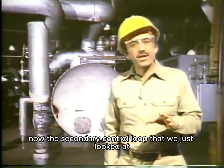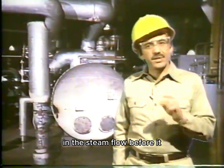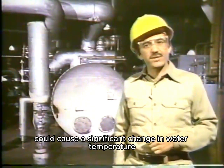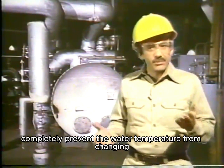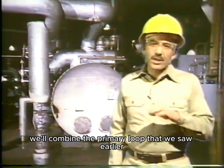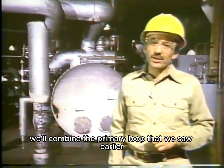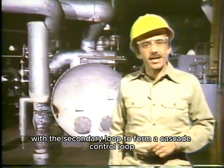Now, the secondary control loop that we just looked at was able to correct a disturbance in the steam flow before it could cause a significant change in water temperature. But it may not completely prevent the water temperature from changing. For this reason, we'll combine the primary loop that we saw earlier with the secondary loop to form a cascade control loop.